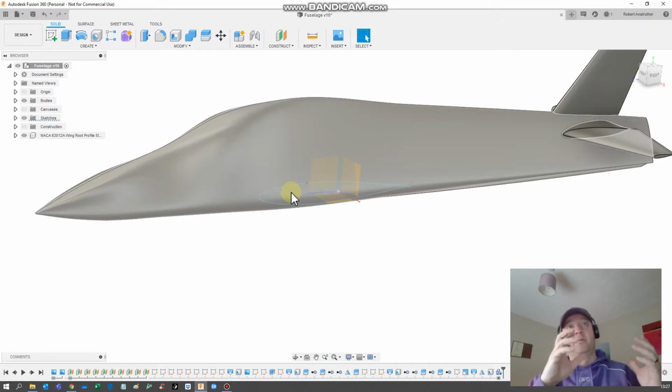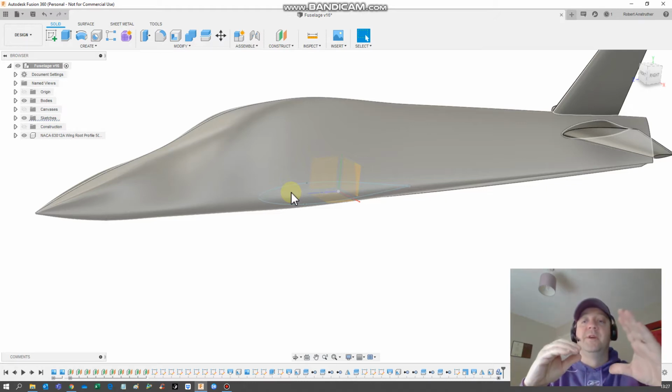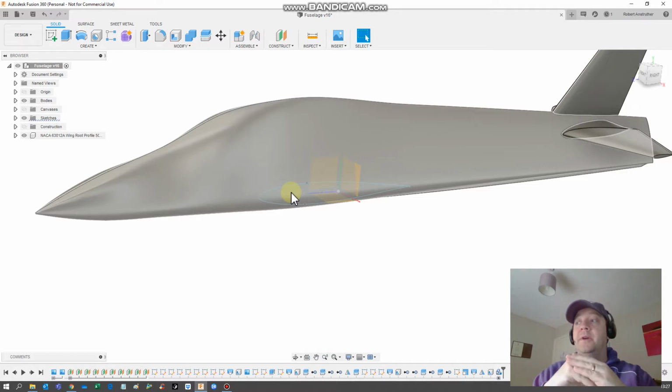But there's another reason for it, which is when you make a mold, you want the mold to be, if I could explain, conical. Say this was the mold and this is your part. So when you pull the mold off, it comes off the part easily. Whereas if you've got something with a lip in here, when you try to pull your part out, the lip stops it.